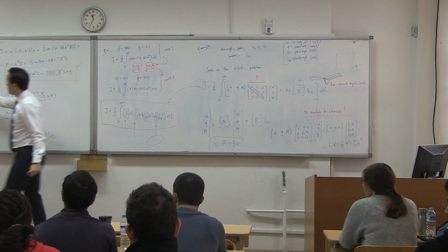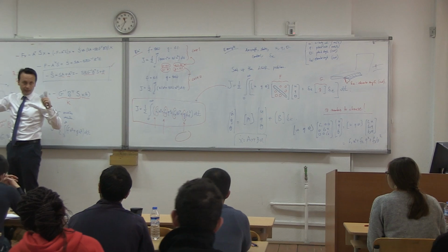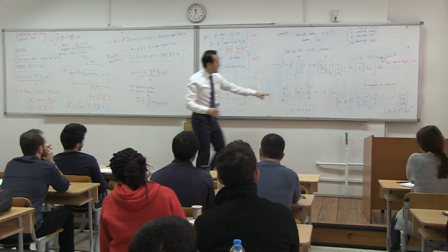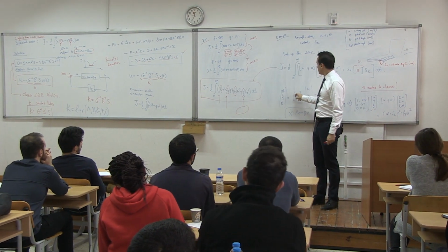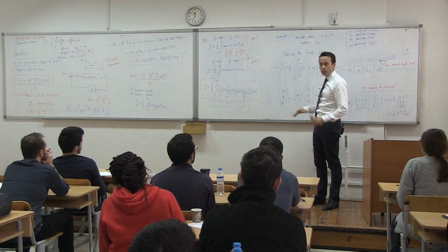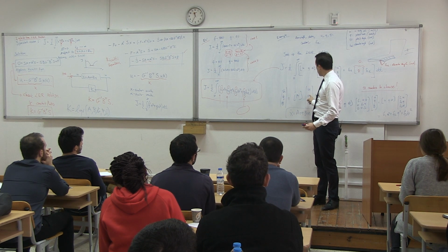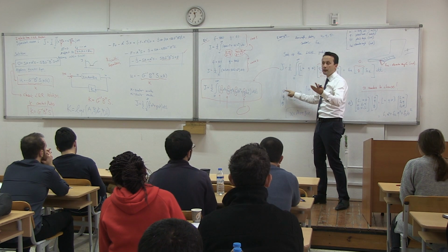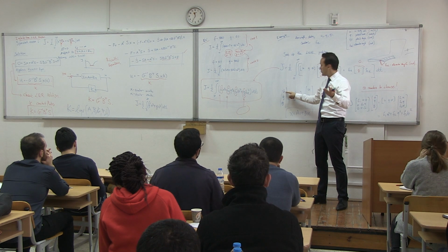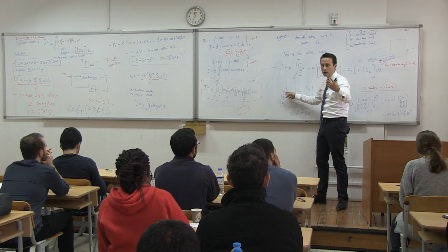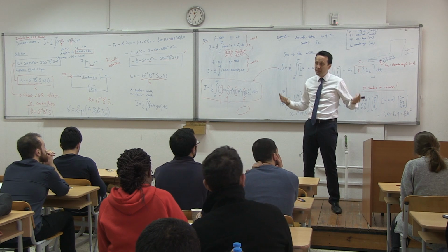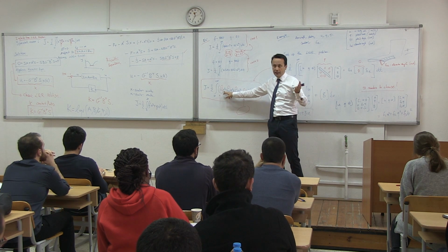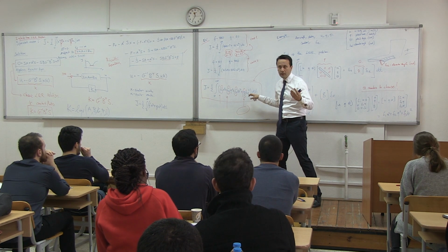Yeah, but the perturbation of U, when you linearize it, you will see that the corresponding derivative in the A matrix here will be a larger number, right? Because a small change in Q will make a large change in U. Let's put it that way, right? A small change in Q will be a large change in U. So any change over here will make a large difference in U. And large means 1 meter per second might not be very large in real life. But for the optimization problem, 1 is already very large because the rest is radians.